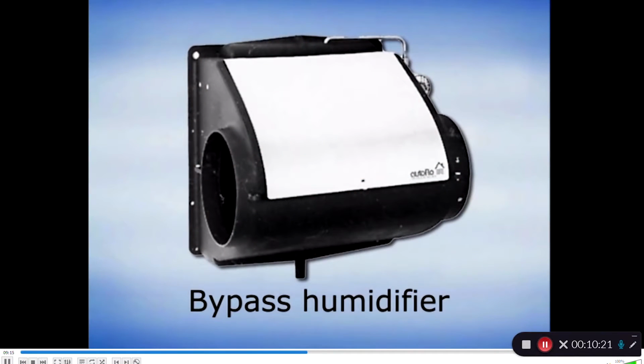Evaporative humidifiers are available in a number of different styles. The bypass humidifier is mounted on either the supply or return duct of the forced air system. Piping is connected between the humidifier and the other duct, creating a connection between the supply and return ducts. The bypass humidifier contains no fan or blower and relies on a difference in pressure between the air in the supply duct and the air in the return duct to supply the needed airflow through the humidifier.